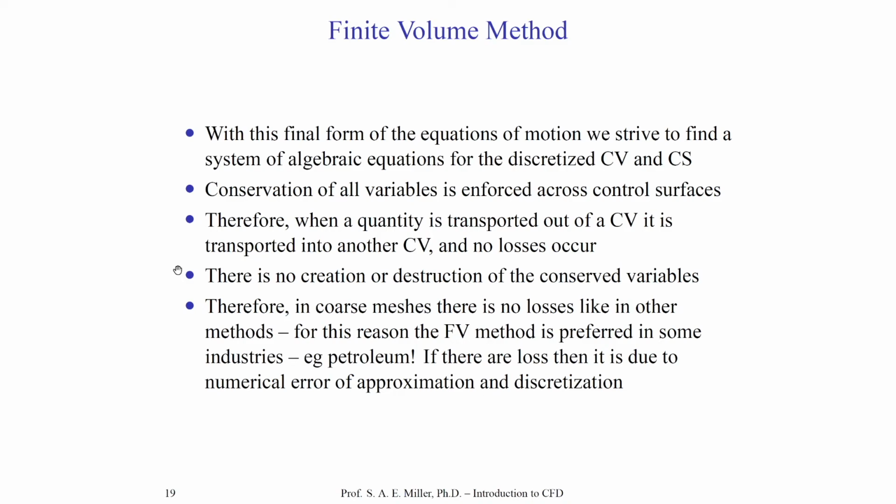So the finite volume method is very, very popular in, say, the petroleum industry because there's no losses and accountability of the product is perfect. Even with very coarse volumes, you could have a control volume and computational domain consisting of one element or volume. This is exactly what you've done in your fluid dynamics or aerodynamics classes before you took this class. That is, you have used Reynolds transport theory and you've essentially discretized and solved numerically using the Reynolds transport theory, which is like a volumetric reduction of the Navier-Stokes equations.